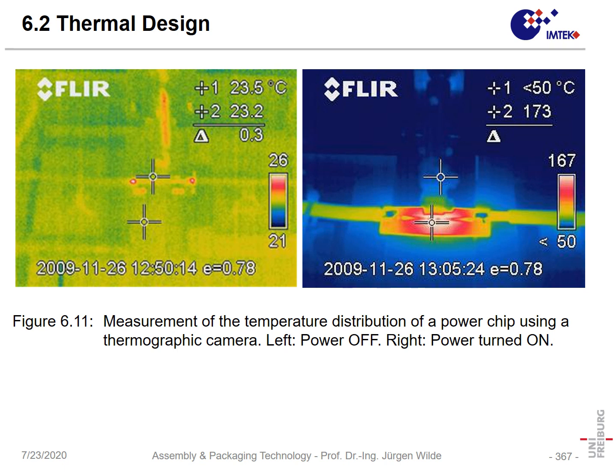On the other hand, it also could be that big differences in the emission coefficient could affect the indicated temperature here. So that means that is cold. Here we can also see we assume an emission coefficient of 0.78.